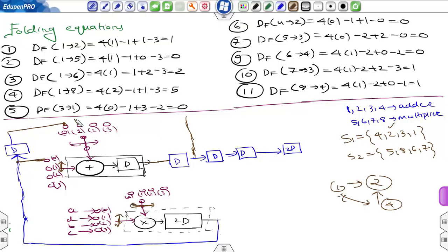the output of this adder should be connected to switch number 1, because now the adder will execute the task of adder 2 in the first cycle of an iteration. And second is 4 to 2. For 4 to 2, zero delay elements are required, so no external delay is required, so directly connecting this to switch number 1 of the second input.